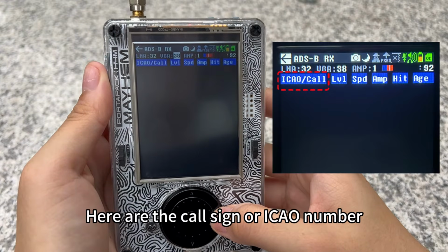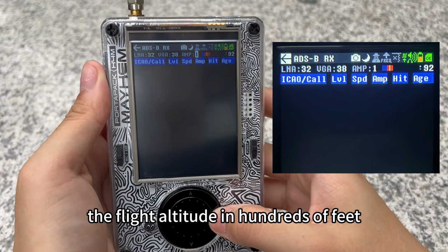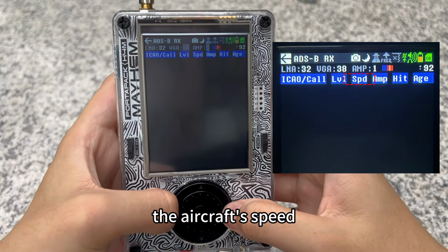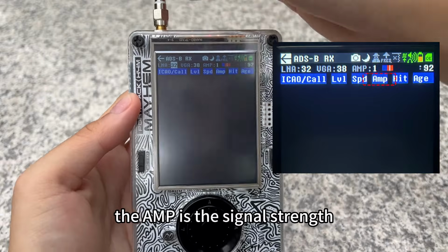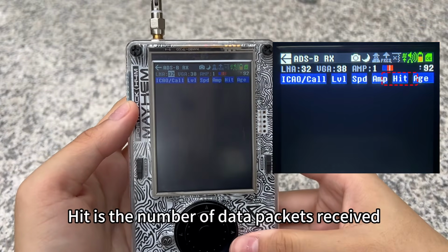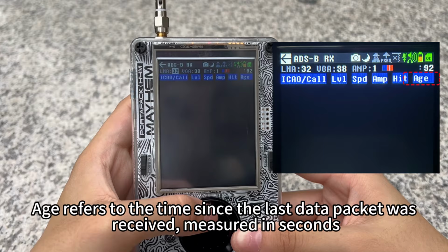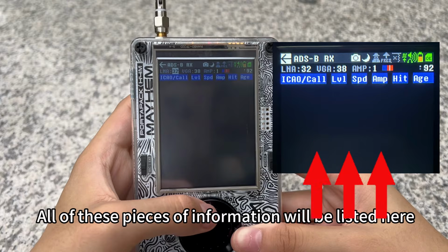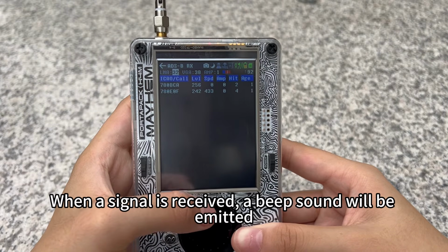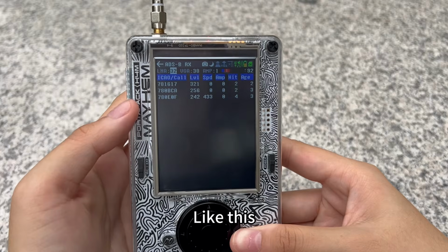Here are the call sign or ICAO number, the flight altitude in hundreds of feet, and the aircraft speed. The amp is the signal strength. HIT is the number of data packets received. Age refers to the time since the last data packet was received, measured in seconds. All of these pieces of information will be listed here. When a signal is received, a beep sound will be emitted, like this.